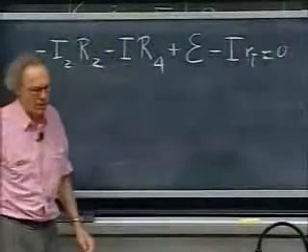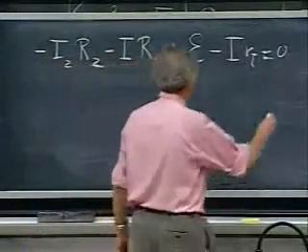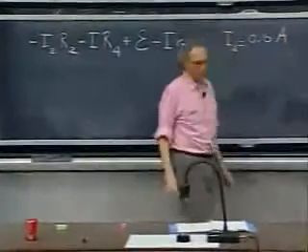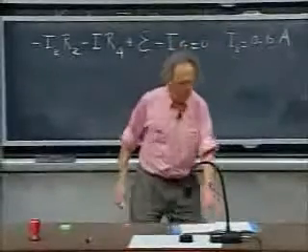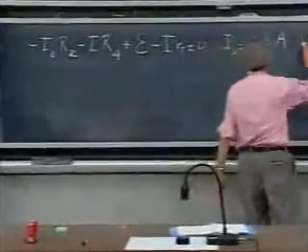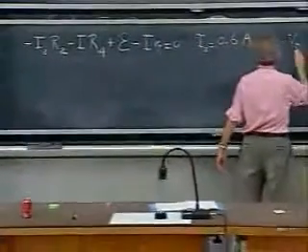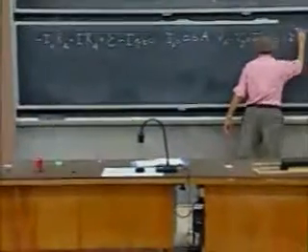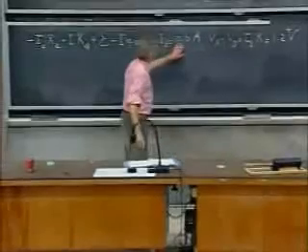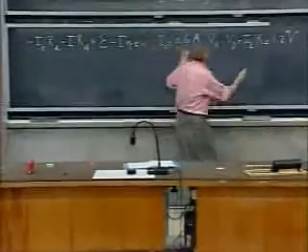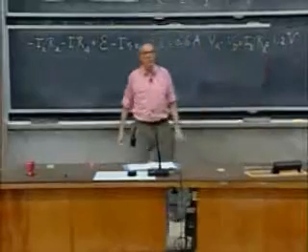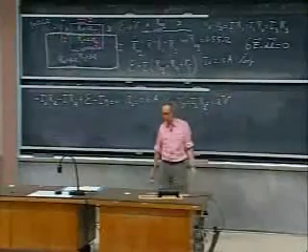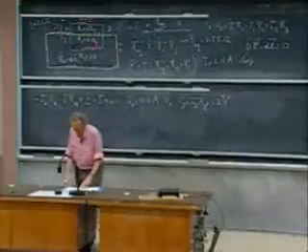That's the 2.15 amperes. And so you'll find now that I2 becomes 0.6 amperes. And so you know now that VA minus VD, the potential difference, which was I2 R2, is now going to be 1.2 volts, because I2 is 0.6 amperes, and R2, there's a 2 here, is 2 ohms. So it's 1.2 volts. The 1.2 volts is also I1 R1, and it's also I3 R3, so you get I1 and you get I3.